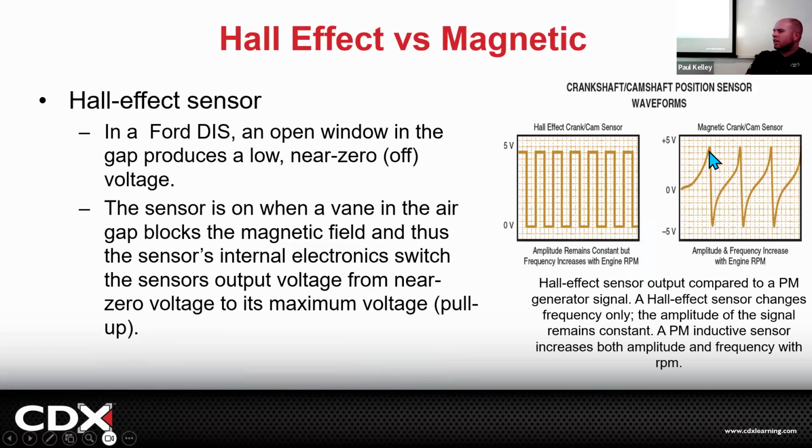This is a little harder to tell exactly where the part is, but we still will occasionally see a magnetic sensor. The magnetic sensor just creates an AC current when the tooth gets close. But the Hall effect sensor is like a powered, active, very precise, fast sensor that works all the way down to 0 RPM. When you're close to 0, the lines get so vague. It's hard to really precisely control it at slow speeds. So we've gone more to these, but they cost more, right?